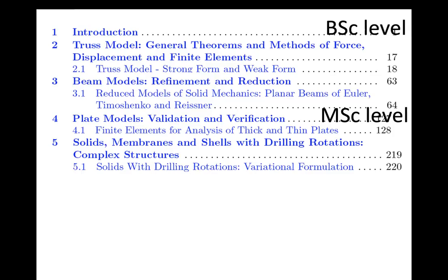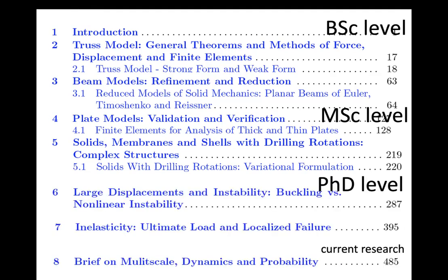And then also when you are doing the connection between solids and structures, you need to enhance the formulation of solids. This is what I presented to you yesterday quickly: membrane elements with drilling rotation, with rotational degrees of freedom, so you can connect easily with structures. This is also illustrated here. I would say this is the knowledge that you look into at a more serious master's level. And then there are a number of topics you deal with when doing the PhD: large displacement instability, buckling versus nonlinear instability.